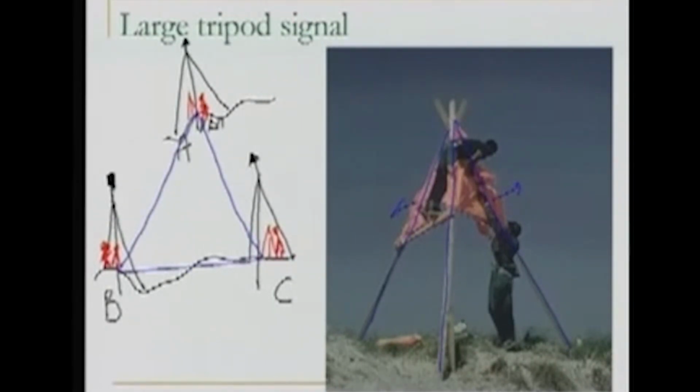Now the thing is, under this tripod there is somewhere the point, the station, and we will erect our theodolite, or the total station, in such a way that its vertical axis is passing through the point here. So the facility which this kind of tripod gives is that someone from the other station can bisect this tripod. This tripod is also centered on this point, while at the same time someone is taking the observations here. There is a person who is standing and taking the observations.